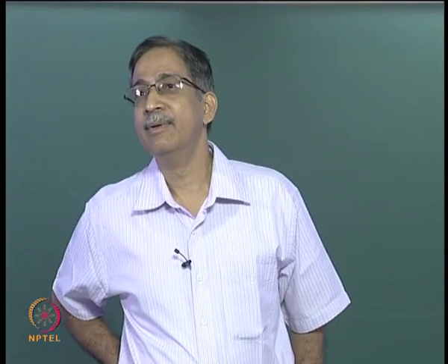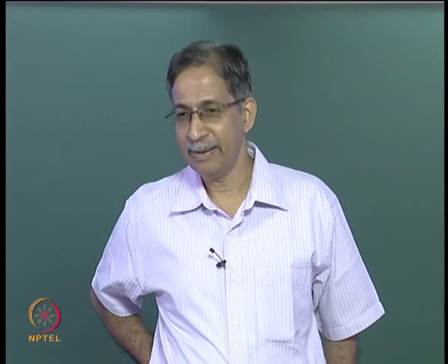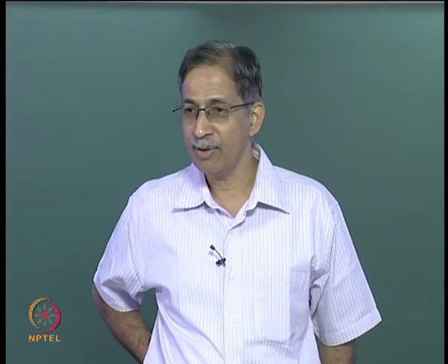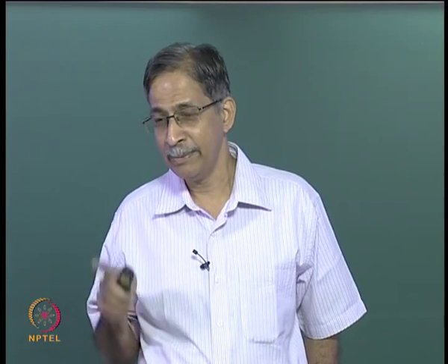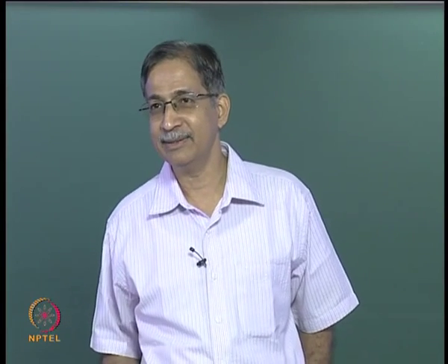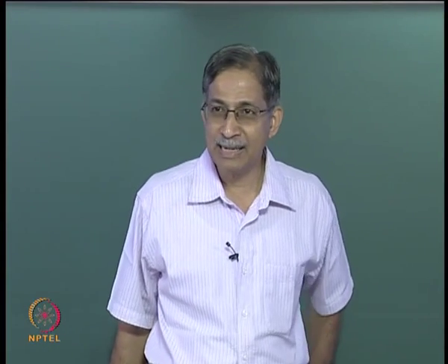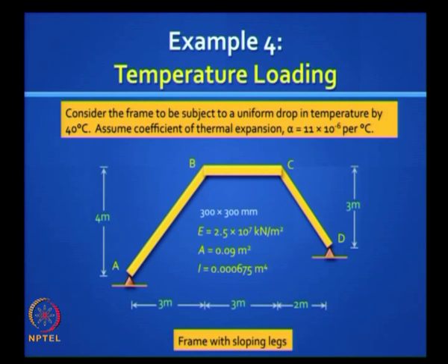or slope deflection method, not moment distribution, because moment distribution is not good when you have sway. You will find that they are almost identical. This is more accurate because you are accounting for axial deformation. We will do the same problem by the reduced element stiffness method, where we ignore axial deformations and compare the results. Okay, here is one last problem, a really interesting problem.